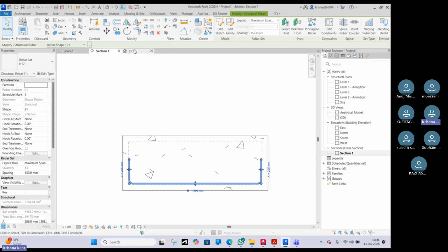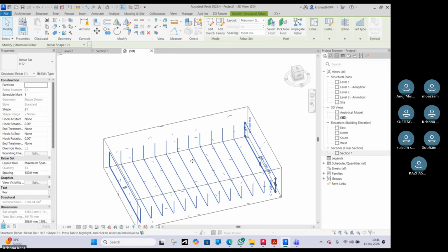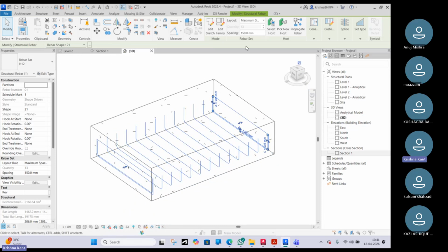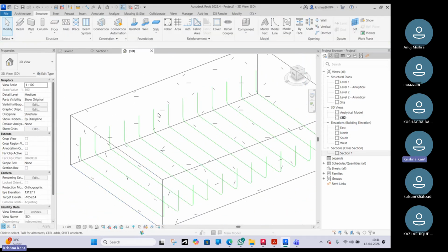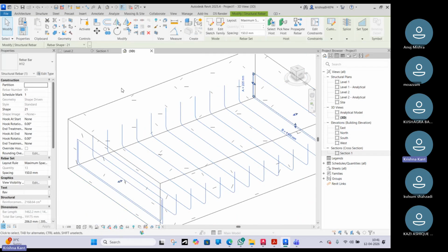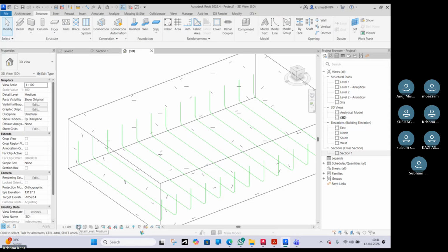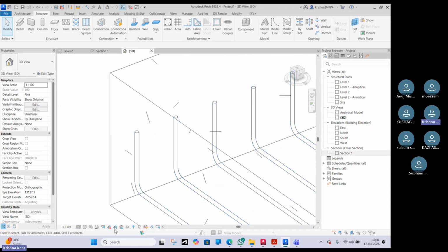And then when you see it in 3D, you will see the rebar which was placed singly is provided all along the horizontal direction, with spacing 150 mm center to center. Now this is shown very thin right now because we have not checked the fine detailing option. If you check this fine detailing option, you will see the actual dia of the bar.